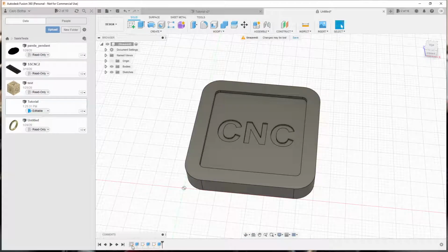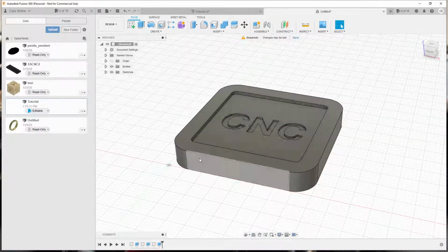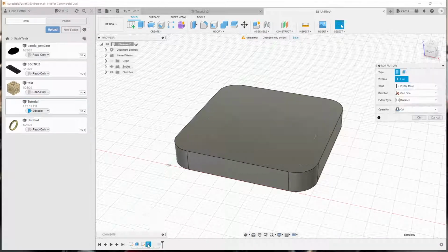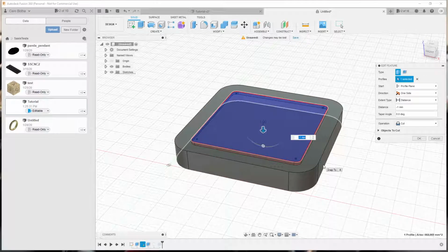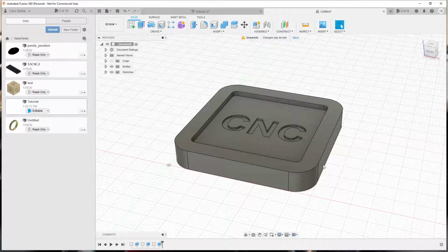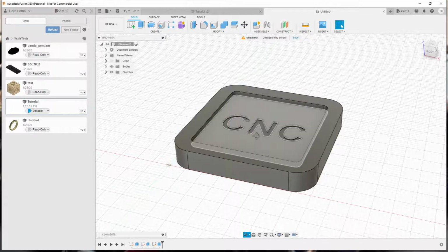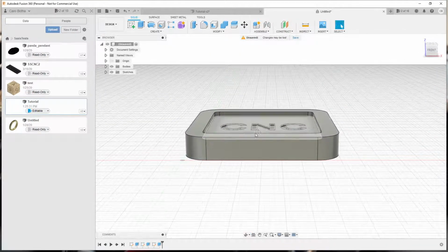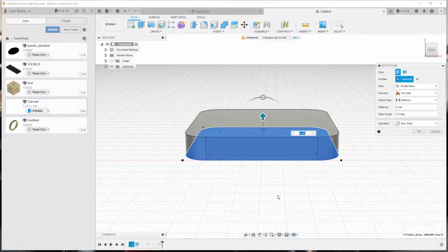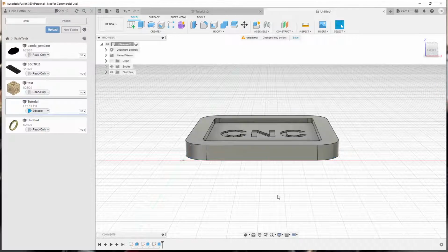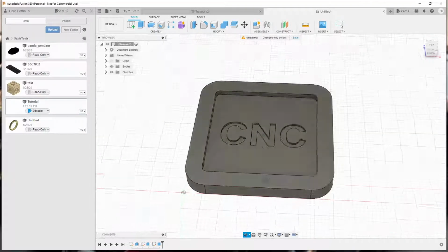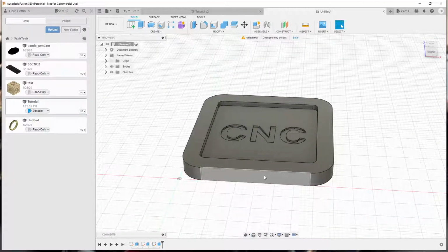And you'll notice that all the way along, it changed for me. For some reason, we decided that that 1 millimeter wasn't enough down. That was this extrusion here. So we double click it again, and we say I want minus 1.5. And you see that it's increased that, and it redid all the work to change all the booleans. Everything is done again. And similarly, I can come back to this one and say that I no longer want it 6 millimeters high, I only want it 4 millimeters high. And the whole drawing will adapt. Super, super, super powerful.